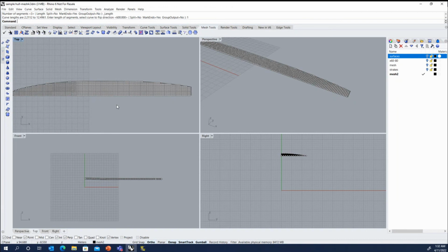Now, the nice thing about doing it that way is you're not limited to a series of planes that are parallel to one another. It's doing a girth along the curve. Now for a deck or a bulkhead, it's not so much of an issue. But when you're dealing with the curved surface of the hull, you may want to do a girth along the curve rather than an even height increment, which is what you'd get if you did the contours. So that's a nice option there for generating those curves on the hull, and that's what we'll use when we do the hull portion.